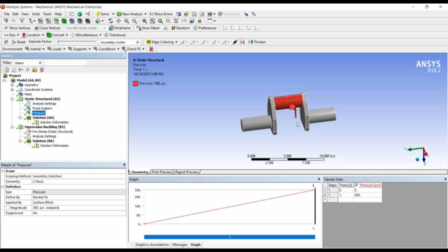Likewise, getting a negative buckling factor is not an error. It is always possible. For example, if you take pressure vessels, water storage tanks and other sorts of examples, you may have a lot of negative buckling factors. So it is up to the CAE engineer to define whether this particular buckling factor is going to be useful or not.